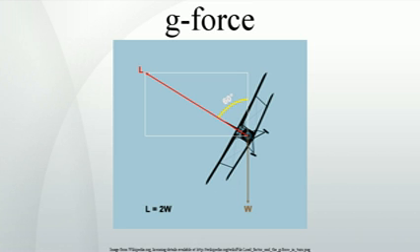If a stationary, single-axis accelerometer is oriented so that its measuring axis is horizontal, its output will be 0 G, and it will continue to be 0 G if mounted in an automobile traveling at a constant velocity on a level road. When the driver presses on the brake or gas pedal, the accelerometer will register positive or negative acceleration.